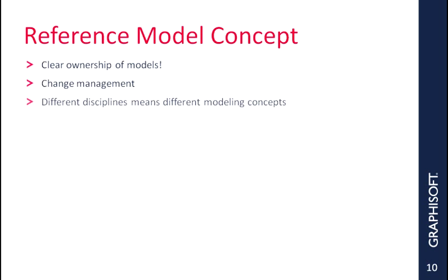The reference model concept is the most important workflow concept used throughout model export, import, and change management. Each discipline is responsible for the creation and development of its own model. Reference model means that a discipline, let's say the structural engineer, uses the architectural design model for the basis of creating the structural model. The structural model will be created as a standalone model, yet some initial design information will be taken from the architectural model.